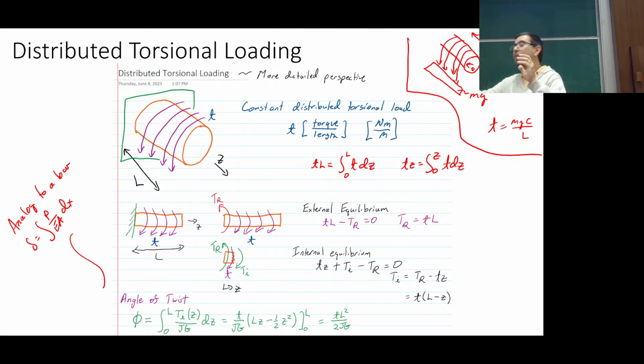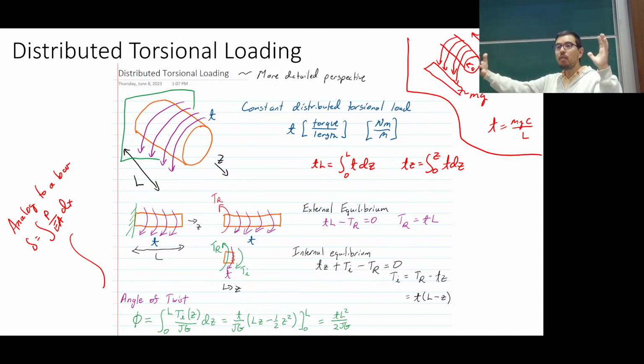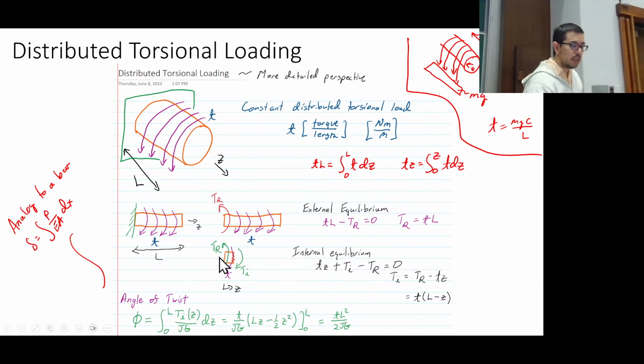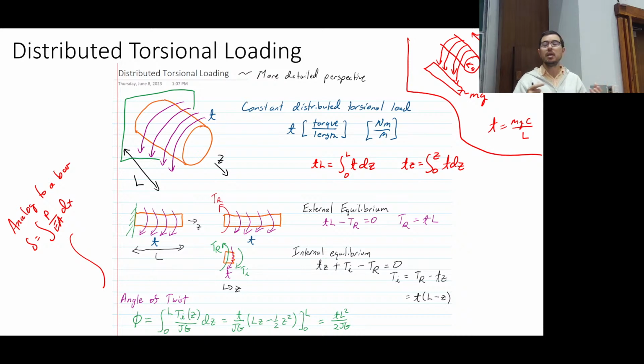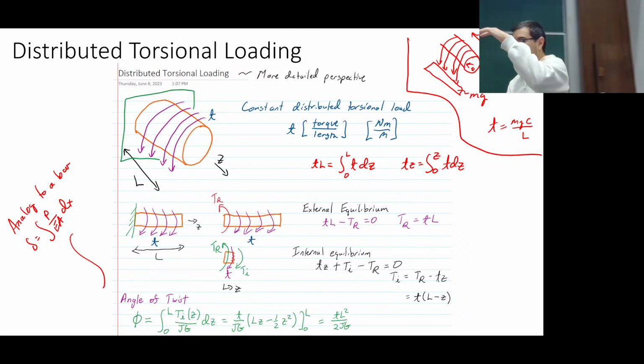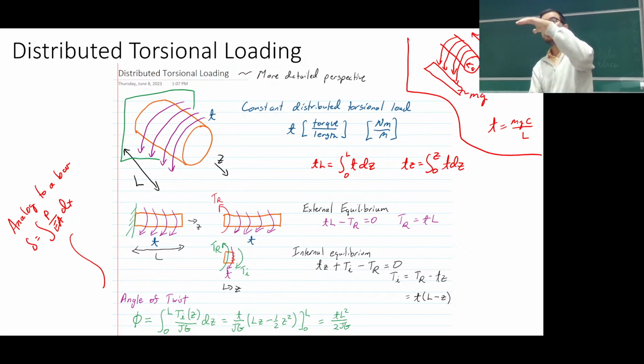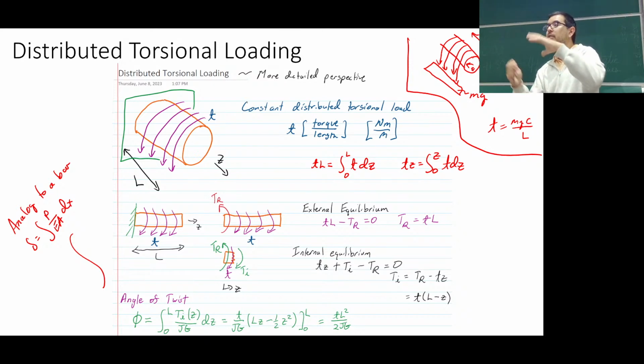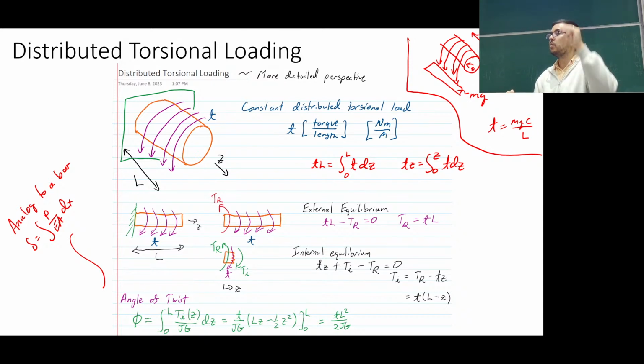I didn't need to know the reaction force from the get-go, or calculate it out. Or if I have a hanging bar, it can also be easier, because when I'm doing my slices, I don't need to know what the reaction force is from the ceiling acting on the system.